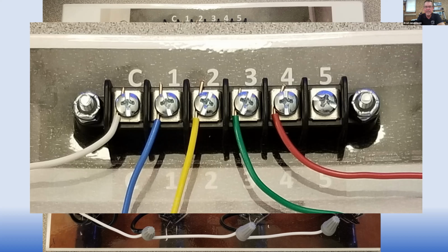Absolutely. And so this is key. That's exactly right. If we put the wire here on the left side, as we tighten this screw down, it's going to pull the wire tighter into the screw, making a much better connection and making it less likely to arc or anything else like that. If you mount it on this side, it's going to have a tendency to push the wire away. So thanks, that was spot on.